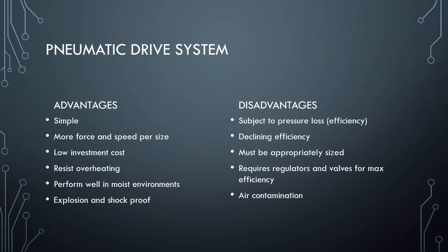There also is a lower investment cost. Remember I said that an electronic drive system has a really high investment cost, although the maintenance is a little bit lower. Pneumatic drive systems are almost the opposite. It's relatively low cost to get this system set up. But over in our disadvantages, it does cost a little bit more to maintain.